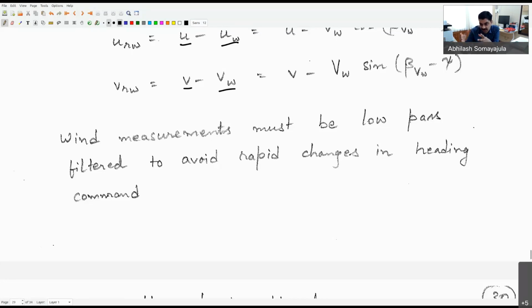So what we can do is take these wind measurements, pass them through a low pass filter, and then use those values to predict our estimated tau wind hat, right? That way we compensate only for the slowly varying components, and any small variations here and there are not going to affect us much, since we are able to disregard them in our control room.